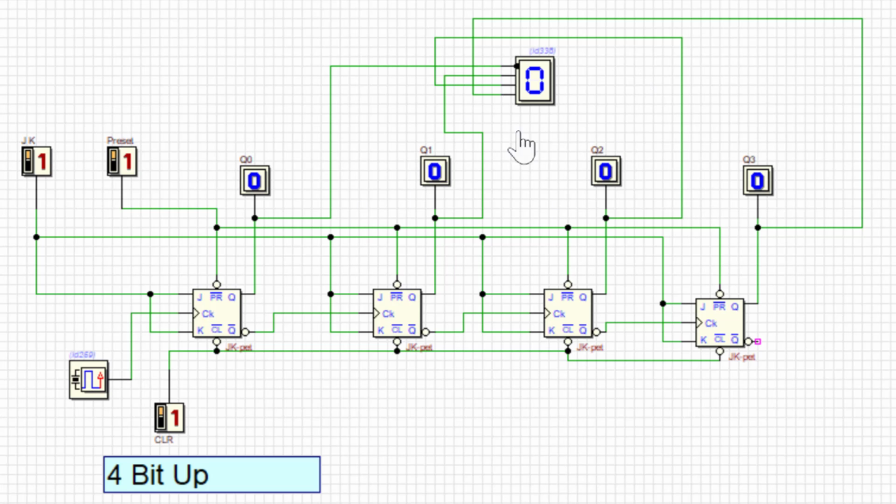So this cycle will repeat as long as you provide the clock signal. So this is how you can design the up counters. Wherever I want to reset my counter, suppose I stop here, now 7 is there in my registers. Now 7 is the output display. I can reset it to 0. Again I can start my counting from 0, 1, 2, 3 and so on.